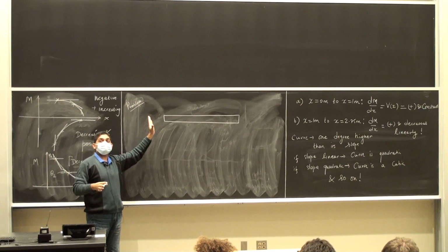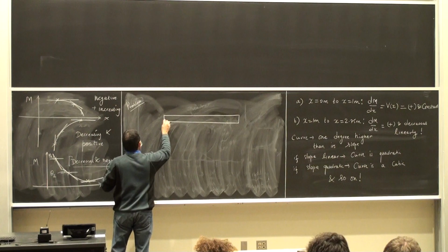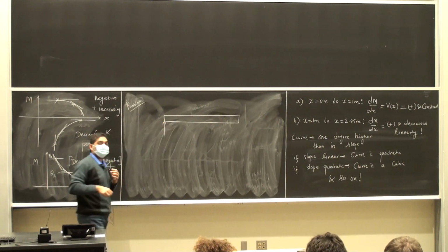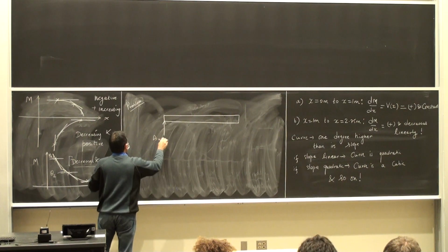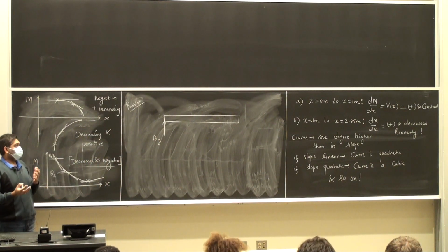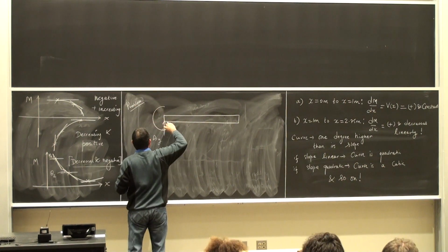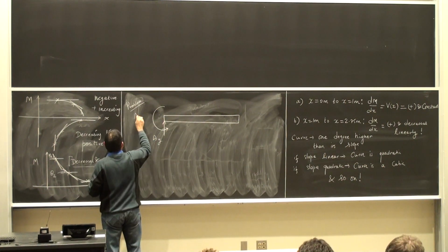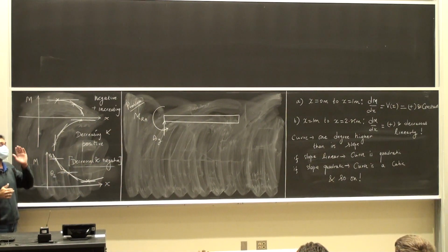Instead, I'm going to show the effect of the fixed support. That's going to give me a reaction force, A suffix y. I'm going to have a reaction moment, MRA, because it's a cantilevered beam.